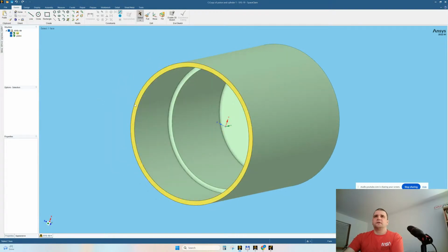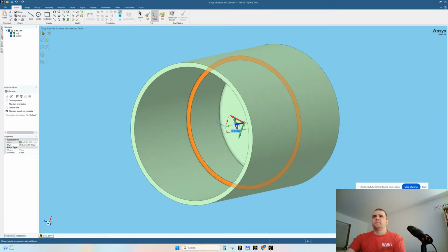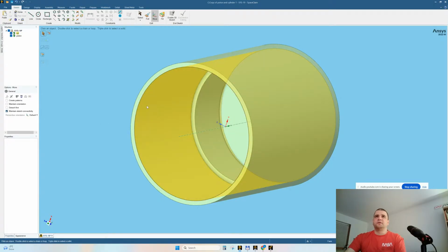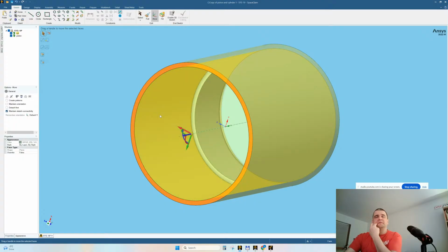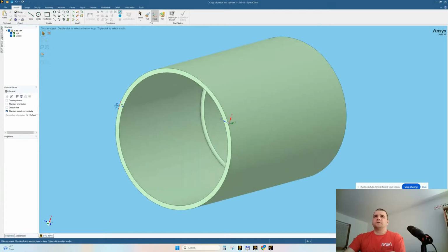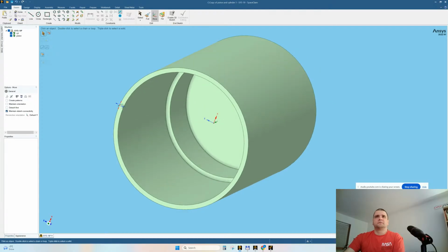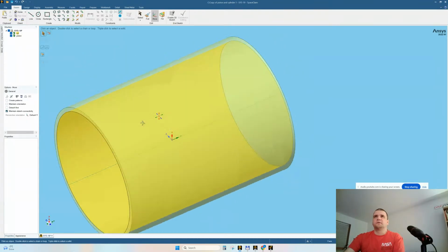It's nothing very time-consuming or difficult, and it opens the occasion for exploration. Just be curious, vary diameter, vary gap, modify material properties, modify film coefficients, thermal expansion parameters from the materials. Just be creative.